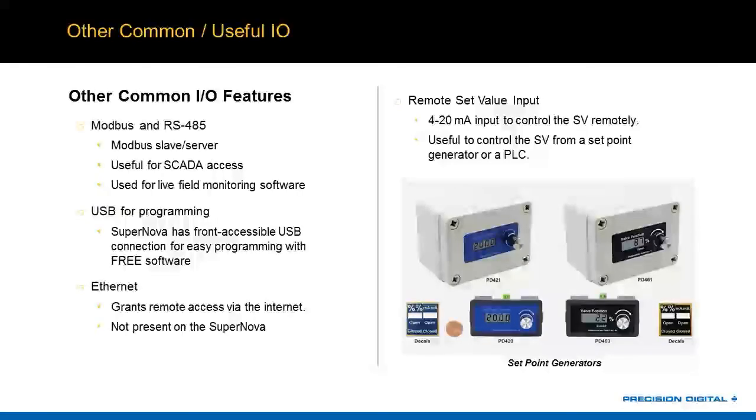Other common I/O features available on PID controllers: you've got Modbus and RS-485. Many now have software. The SuperNovas do as well. We have a really convenient front accessible USB connection on the larger sizes, not on the 16th DIN. On the 16th DIN, it's in the back of the panel, but that's great for going in there with the software and making quick changes after installation. You can also use our PC software to monitor multiple units if you have an RS-485 multi-drop system.